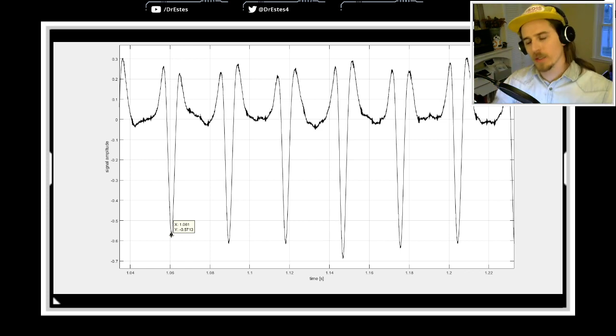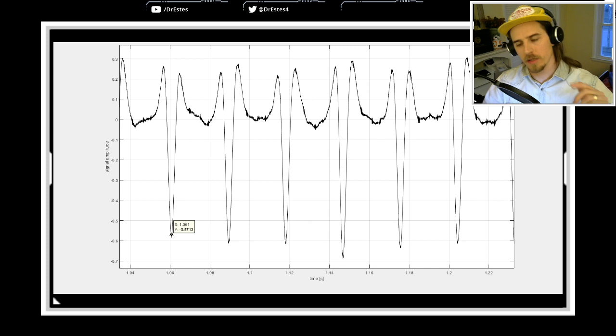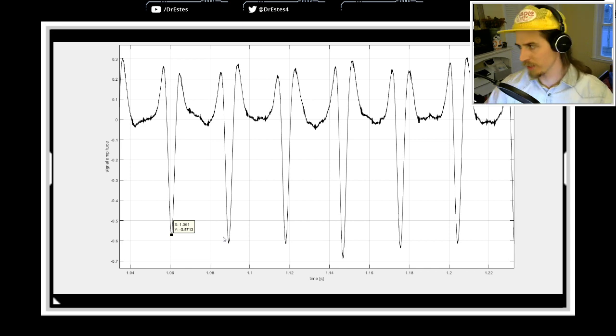So from that, the angular velocity is the rotational displacement over time. So you have one revolution over basically 0.02 seconds. So that gives you the revolutions per second, but I want you to give me the angular velocity in RPM. So you're going to have to do a couple calculations in there.